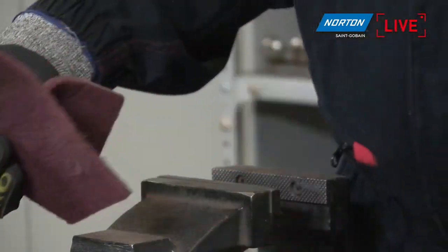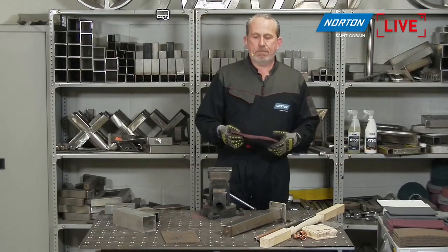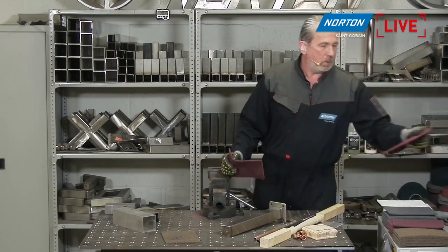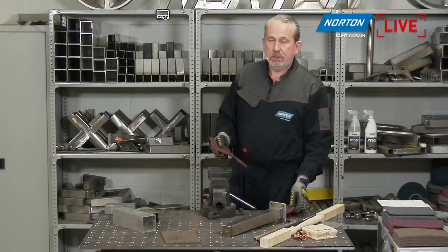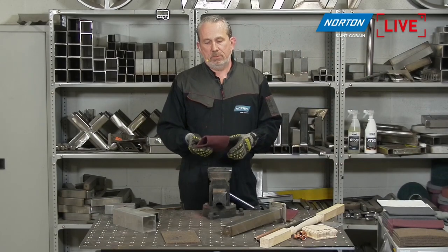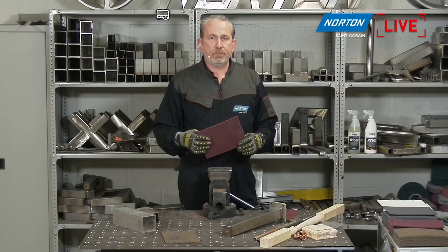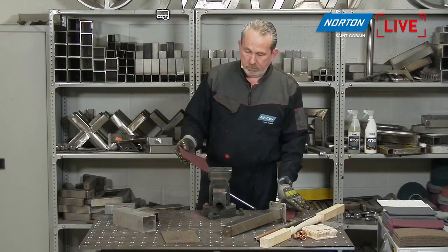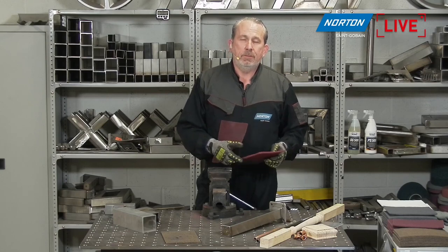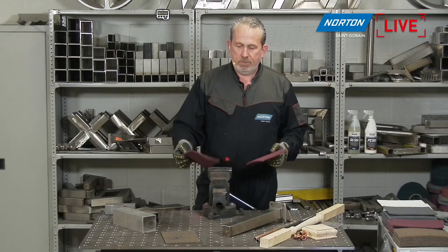Yeah, so one of the great things about this product, you're talking about the finish there, Paul, is the fact that we use finer grits, but a lot more of them. So sometimes in a lot of cases, finish can be sacrificed for an increase in cut rate when using hand pads, but not with this design on this very fine maroon pad that we have. We use a lot of finer grits, and that allows the distribution of resin and abrasive throughout that design, and allows it to give a much finer finish and not have that sacrifice.